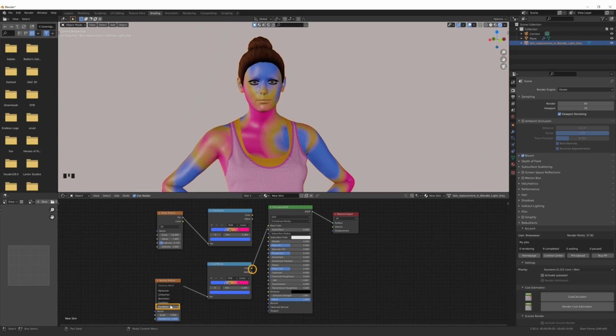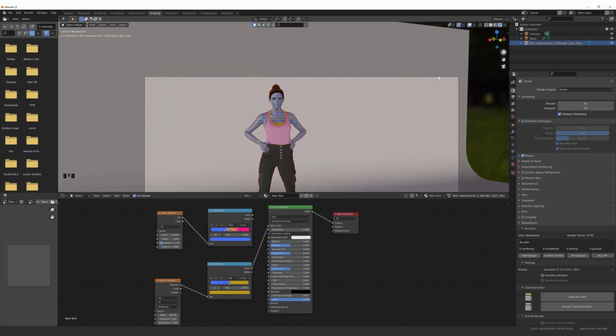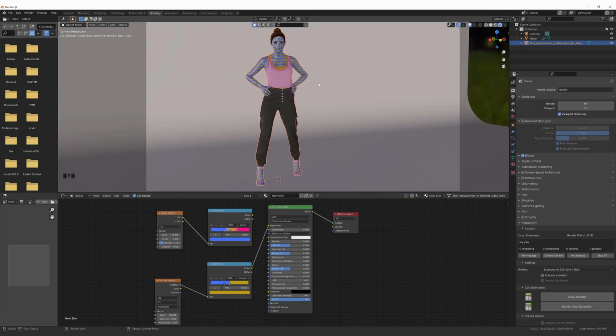Then change the distance on the Voronoi Texture to Minkowski, and delete one of the color stops on the color ramp, setting it to Constant. You can then toggle between the values on the Voronoi texture. By combining different nodes with different settings, you'll have access to an endless variety of materials. If you are new to creating your own materials in Blender, not to worry. There are many useful online resources to help get you started.